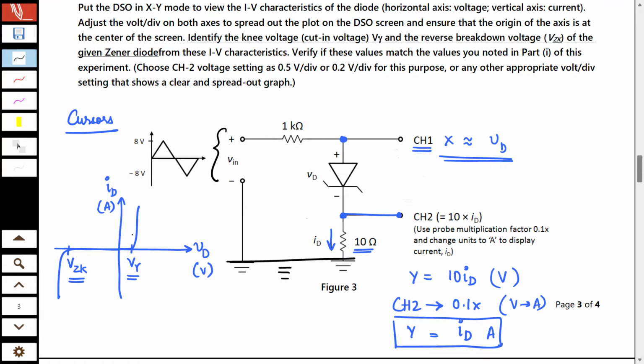So what you should do is select a point, any point on these forward characteristics, and then V upon I. That should give you RF, that is the forward resistance. Right? Know that the point that you choose should not be too much in the very high current region, because here it's almost a straight line, so resistance might come almost zero.